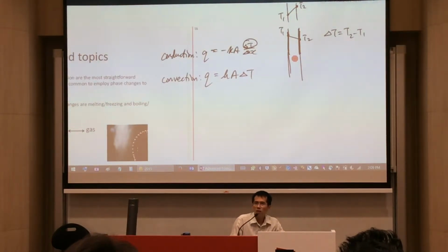So another way to make sure that we have a larger surface area, what we could do is to introduce fins. Now, could you see that this surface area is a lot larger? So if you want to encourage more heat to get transferred over, maybe you will want surface areas to be increased that way.